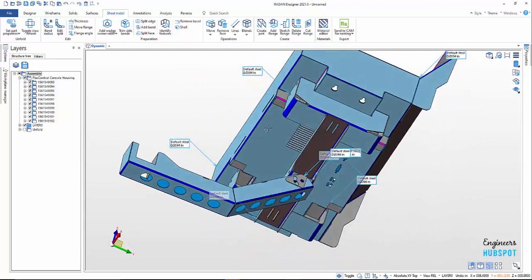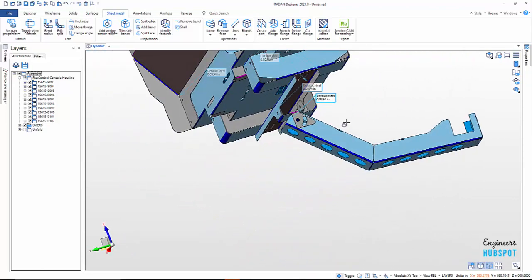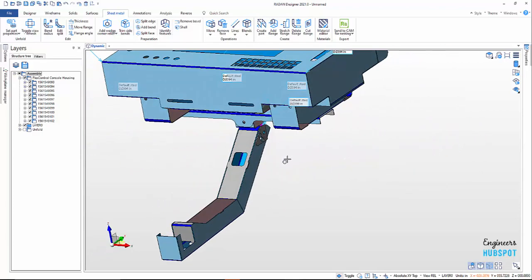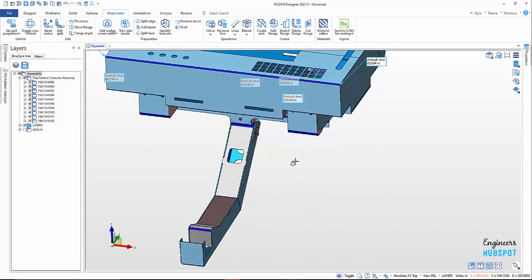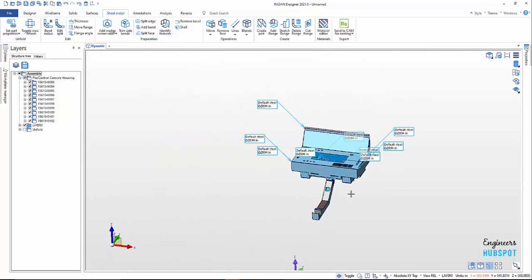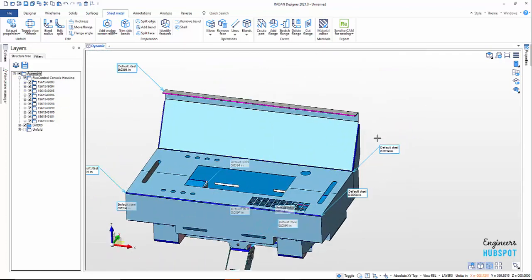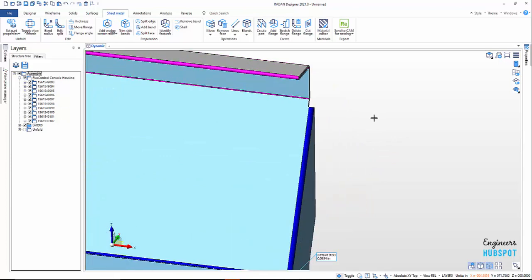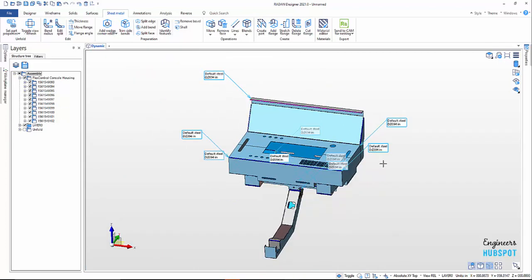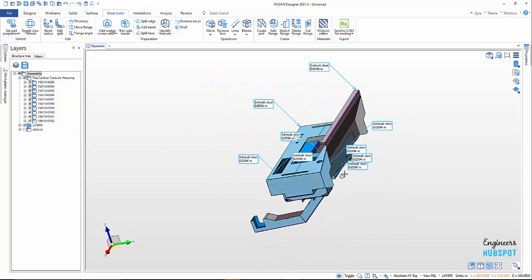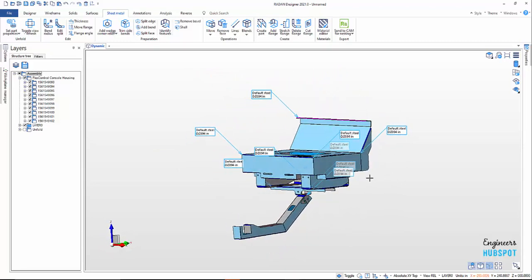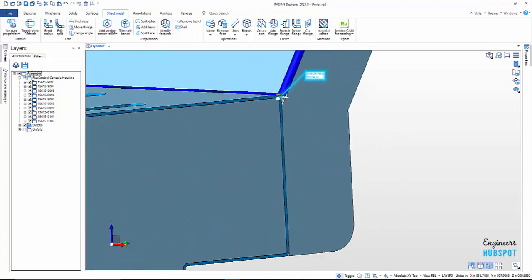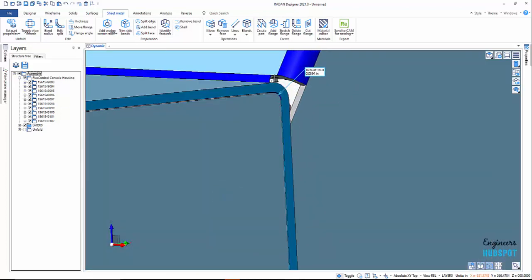So all of these parts must be pretty good, because sometimes you may have a part that is a sheet metal part but you have problems unfolding it, right? And the reason you probably have problems unfolding it, this is one I know for a fact. When I pulled this into Autodesk, I had problems unfolding this because there was a little bit of a face on here.